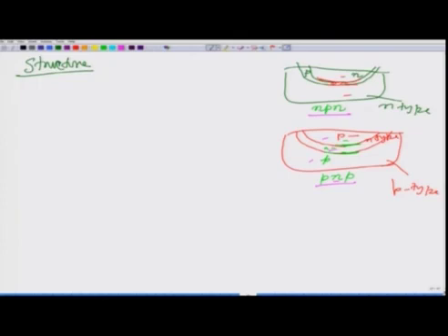So, this is how it is made, and schematically if I take this kind of a cross section, I can show it as we did for the p-n junction. You have a junction here and a junction here, and let us say this is NPN. So, this is N, this is P and this is N, and you have a depletion layer. The same physics will apply: you have a depletion layer here and a depletion layer here, with charges but no charge carriers in the depletion layer. Remember all these things?